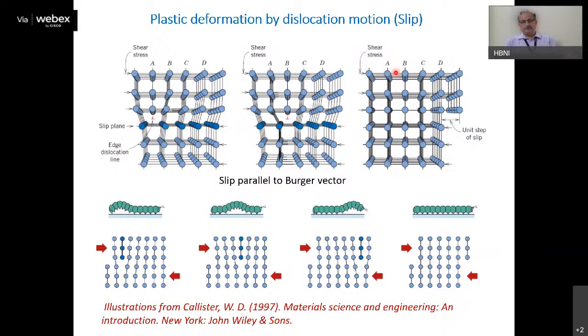So macroscopically, you will see a deformed system. You will have the edge which is at some angle. But microscopically, these atoms have moved in such a way that they have relaxed this stress. Every dislocation will have some stress state, like here it is compressive and here some tensile stresses are there. So they will be relaxed as you apply shear stress, and there is a plastic deformation. This is the mechanism we are studying.